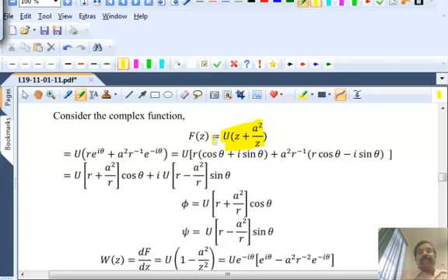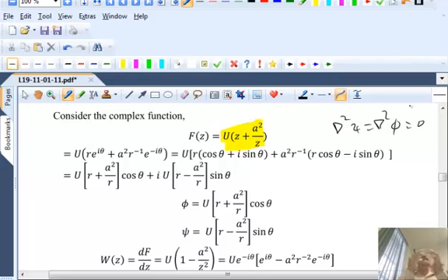Because the equations del square psi equals 0 and del square phi equals 0 are linear, if I have a number of different solutions, I can add them up, I can superpose. The superposed solution, the added solution, will also satisfy these equations. Linearity allows you to superpose the solutions.